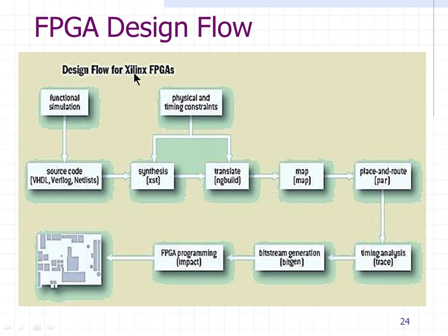This is the FPGA flow for Xilinx FPGAs, but basically it will hold true for any FPGA or even for ASIC designs. Some ASIC designs will have some additional steps, but those other steps are also part of the flow. So how does it work? First, before you start coding in Verilog, you have something called a design specification step. Somebody like a system architect or a design architect will first think about developing a new product. Based on the new product, they will decide whether to develop that part.